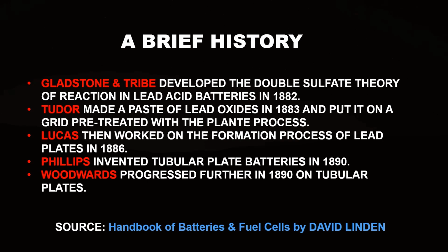In the case of formation, what happens is that, as I mentioned, the lead sulfate of the positive plates becomes PbO2 by oxidation and the lead sulfate of the negative plate gets reduced to sponge lead by the process of reduction. This is a simultaneous reaction known as a redox reaction.